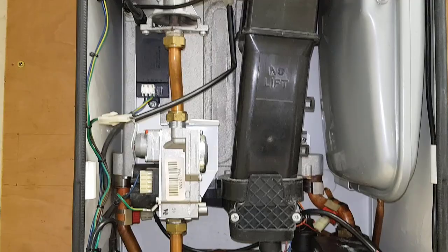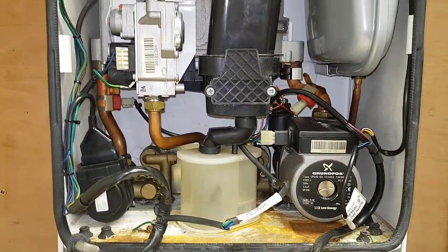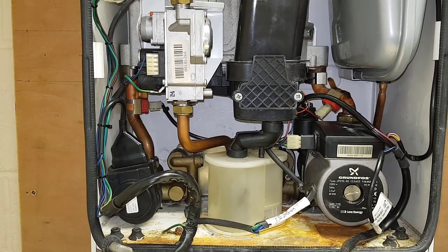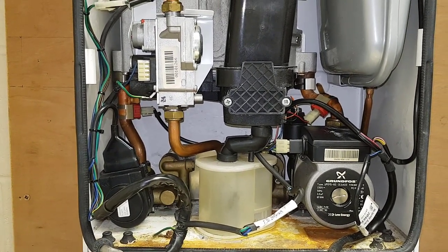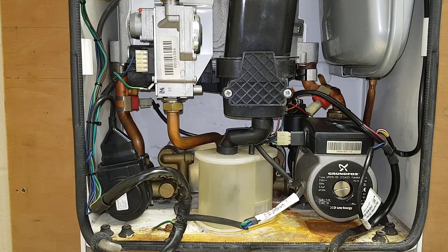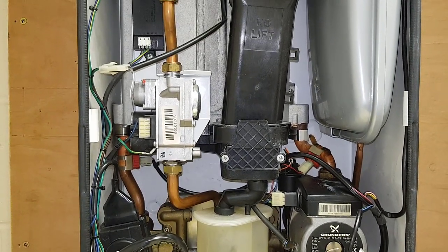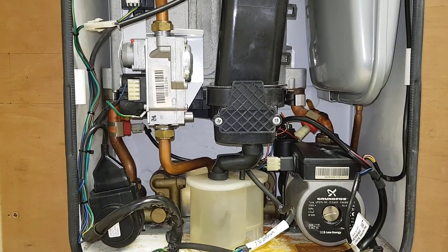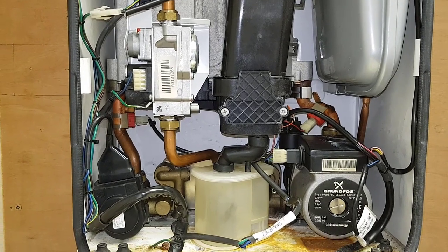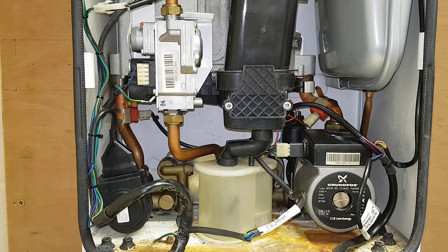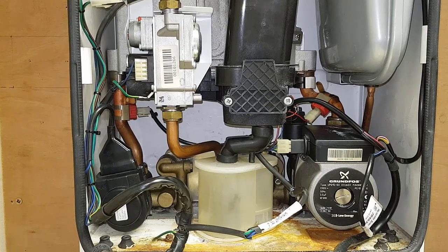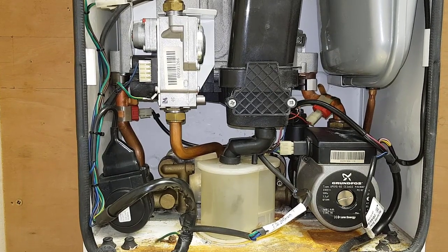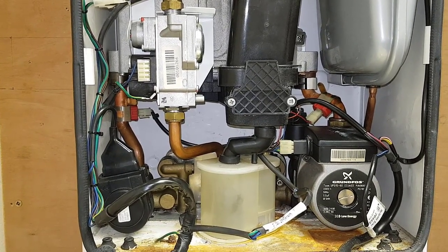All right, cool. So the last quadrant, what's that one? If we're losing pressure or pressure's increasing. Okay, so what would those possibilities be? Expansion vessel. The expansion vessel pipe could be blocked. PRV. Diverter valve cartridge. Check to see if there are any leaks in the radiator valves, or a hole in the radiator.